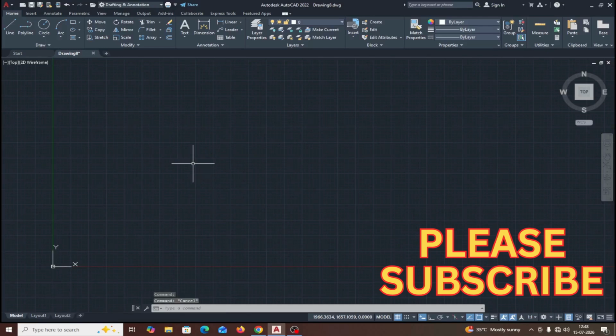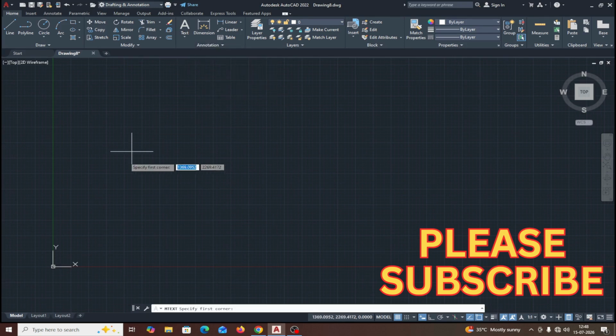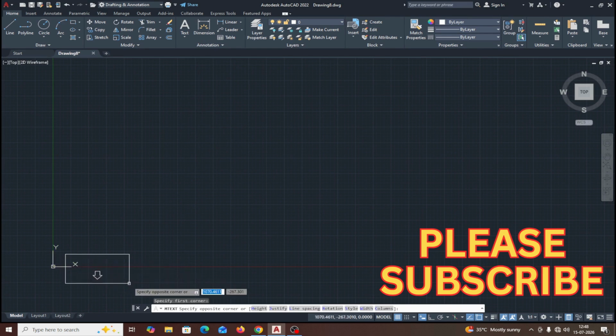Hello everyone, in this exercise of AutoCAD, we will understand about the multi-line text, as opposed to single line. You will find this in the annotation panel in the ribbon bar. Here you will find the multi-line text. In the previous exercise, we have seen the single line text. Select this one, then select one corner point and another corner point.